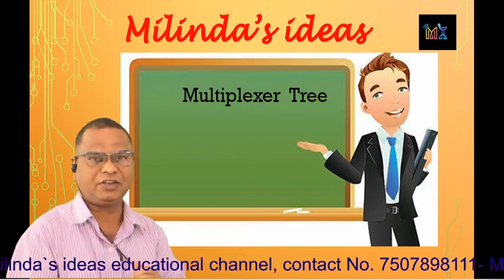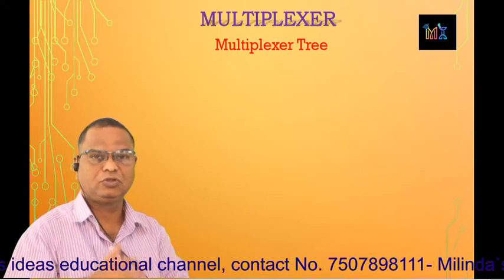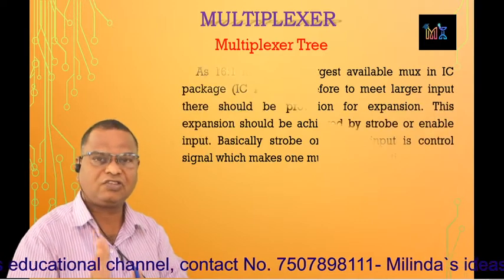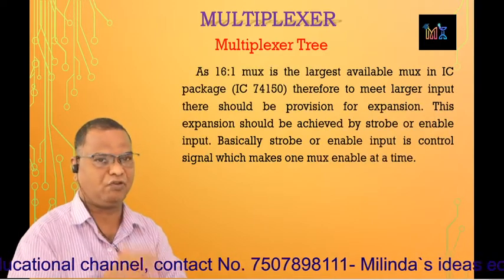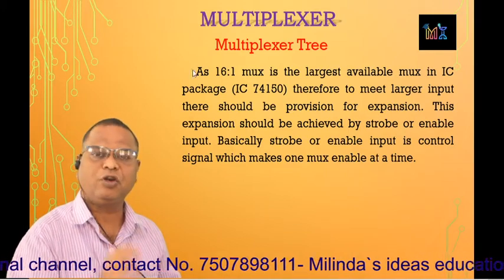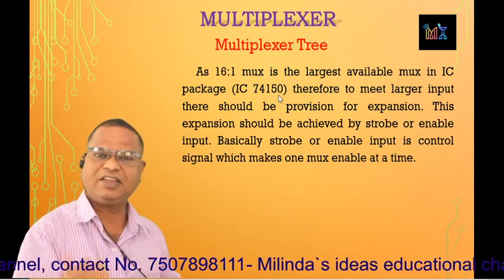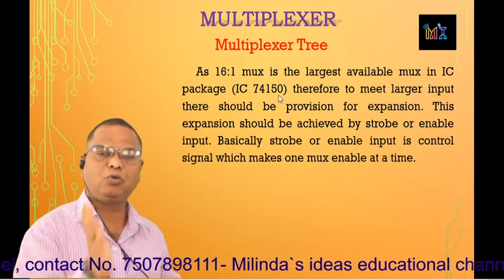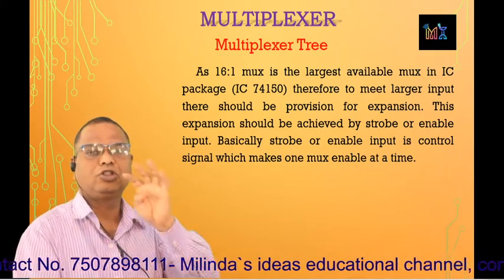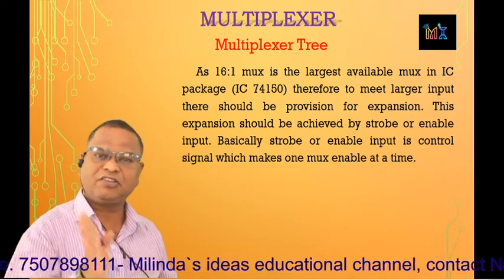It is a multiplexing tree. First of all, what is the necessity of a multiplexing tree? IC 74150 is the largest available mux in IC form. This IC has 16 inputs and 1 output, so it is basically a 16:1 mux. The output of this IC is an inverted input. It has 16 inputs, 1 output, and to select one of the inputs out of those 16 inputs, 4 control lines are required. But it is a 16:1 mux.